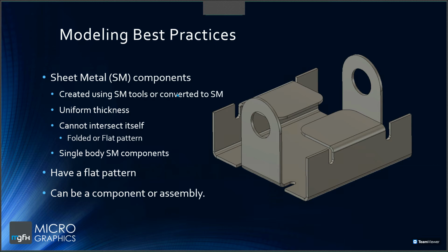And then one of Fusion 360's limits is that you are limited to creating a single-bodied sheet metal component. So each component in my design that is a sheet metal component only has a single body. And the nesting process also only considers the first body in a component. So when you create the nest study, it finds the very first body in that component, and that is the body that is used for nesting.